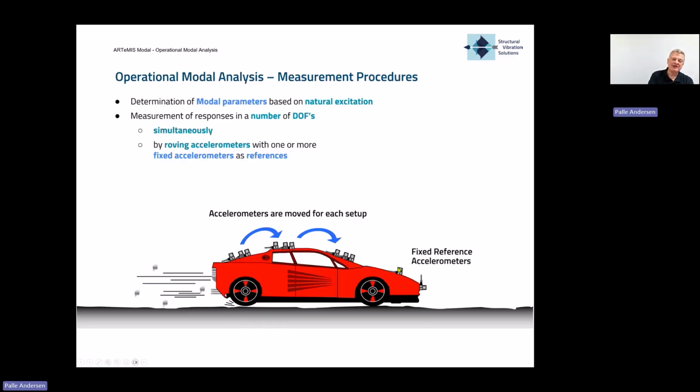That means what we have here is really, really critical, because this is actually what enables us to put things together in a nice way. So first of all, we need to make sure that we have really high quality sensors working here. You should not just take the cheapest strain gauge or something and put it here, and then use nice quality accelerometers in the other locations. Then you will really get some bad results in the end.